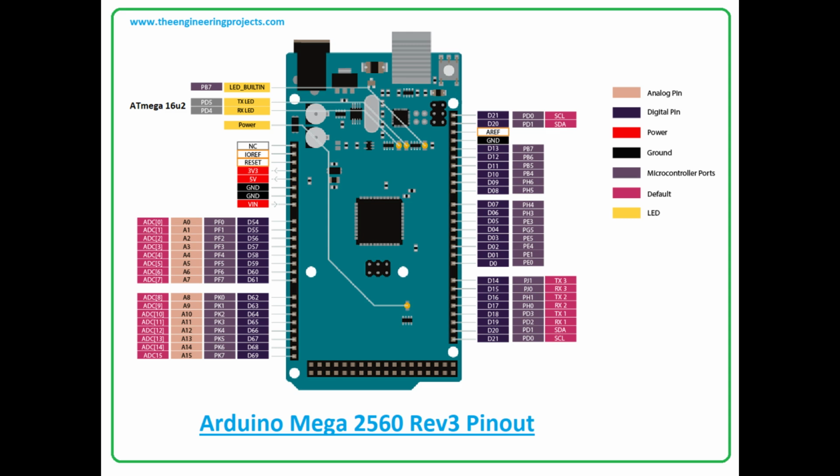In today's video, we are implementing UART serial communication on the AVR ATmega 2560 microcontroller, the chip behind the Arduino Mega. We will be covering two complete tasks. In task 1, an Arduino Mega transmits a number over UART and a second Arduino receives it and displays it on a 16x2 LCD. In task 2, a button is pressed on the first Arduino Mega, sending a character over UART, and the second Arduino Mega uses the character to control an LED, turning it on or off.